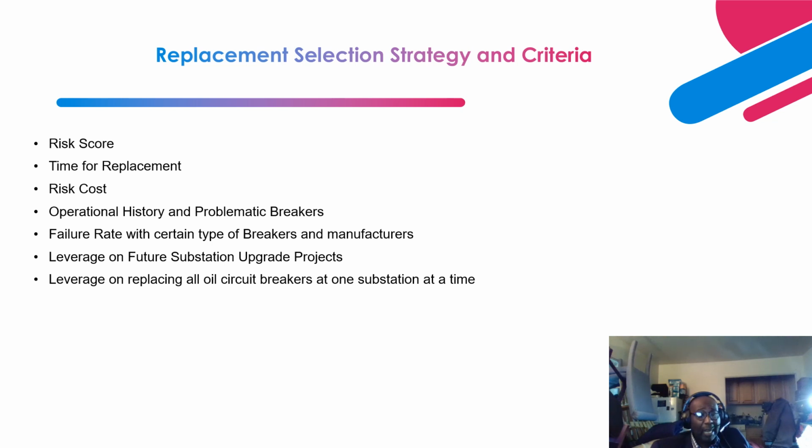As field personnel go out in the field and perform inspection and provide support to field calls, they encounter breakers that are problematic. I'll give you an example of one that had a problem with latching; the latching mechanism was giving us problems. We ended up replacing the latching mechanism. Then other problems started coming up, those were hidden. So this becomes a problematic breaker that warrants immediate replacement.